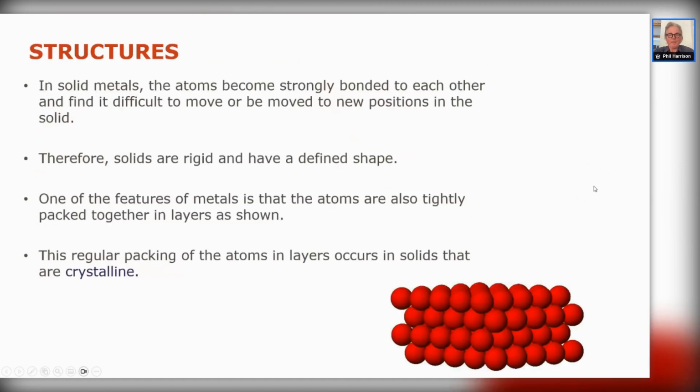Right, metals. Metals are crystalline. They're built on what's called unit cells. The unit cell differs for different materials. There's quite a number of different unit cells or subdivisions, but there are 4 major ones. These define the properties of the materials.